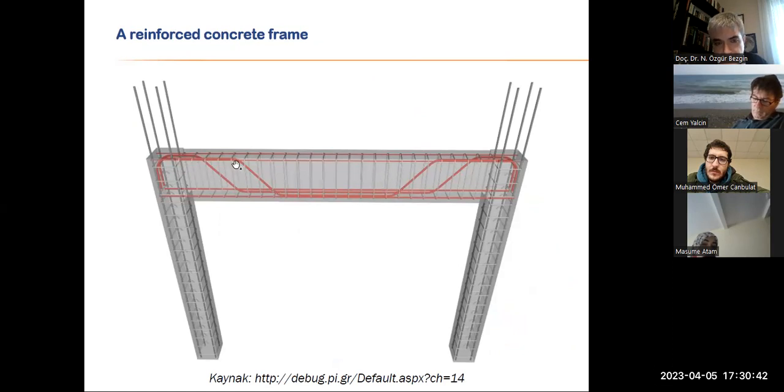For example, over here, we have the tension at the top, tension at the bottom here. So we have this transition for the tensile region, which requires some heavy rebar formation. And the rebar must be capable of doing this. This internal bending diameter is very important, because if it's brittle steel, we cannot be ignorant of that fact.